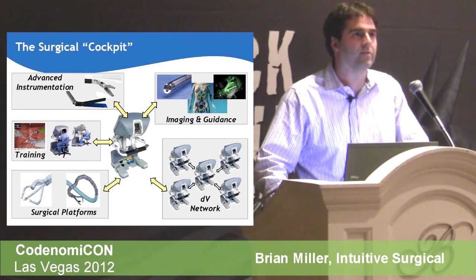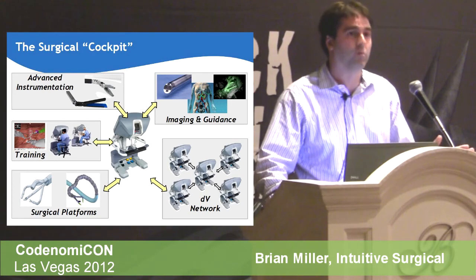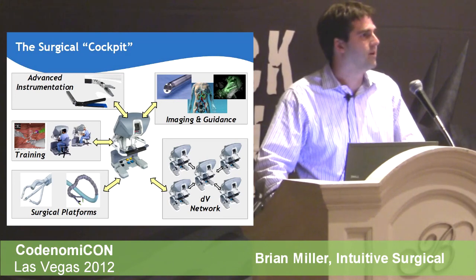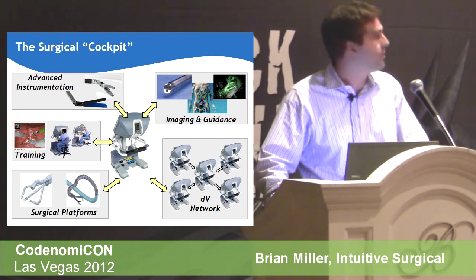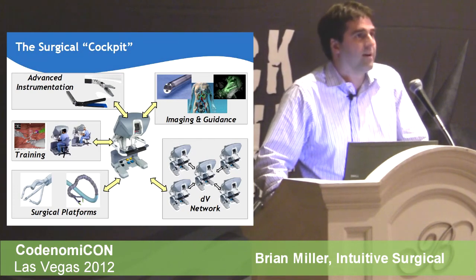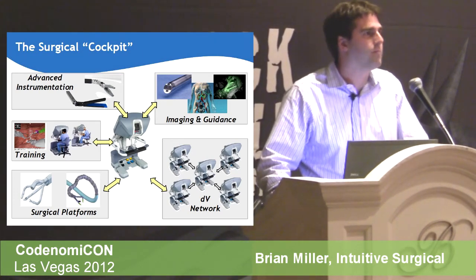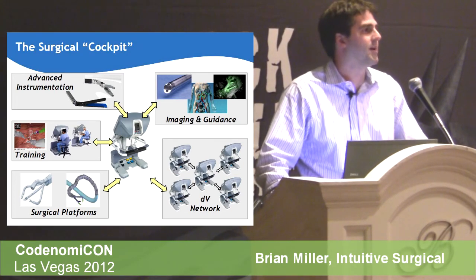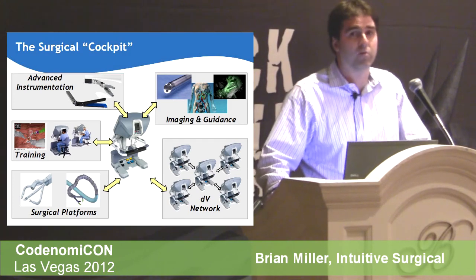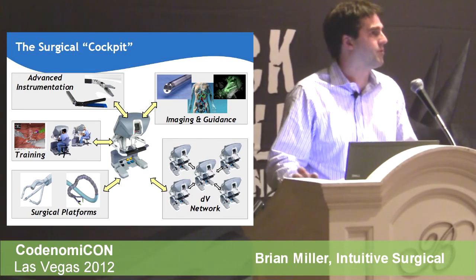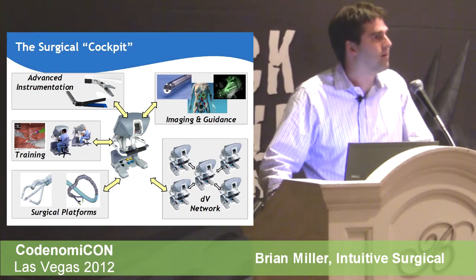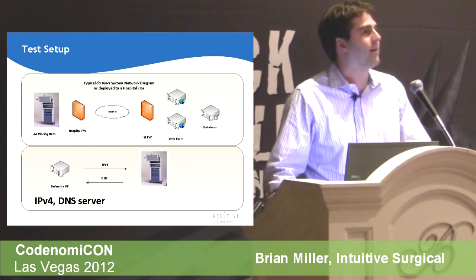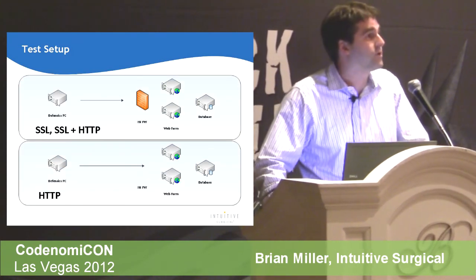We started to integrate that into our testing platform and methodology, so that we can use that type of technology to start addressing that question even more for the network-based capabilities. And then when we get down there, obviously we're building in these capabilities for a reason, and so we wanted to be reliable and robust. But we do have very stringent checks inside of the embedded system, especially for some of the network communication, where if it doesn't understand what's going on or receives a packet that it doesn't recognize, then it will just shut down its network communication, not communicate out any longer until the system goes into a different state.